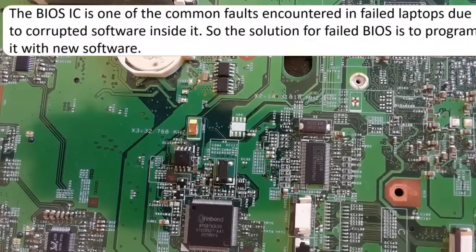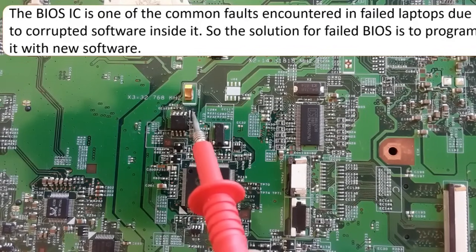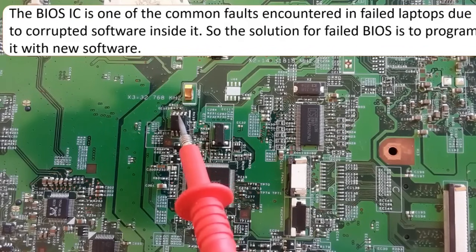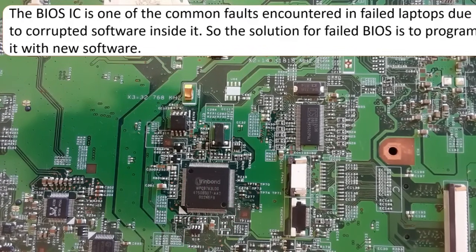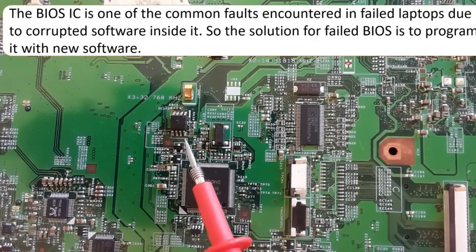See the BIOS, the basic input output system IC. Here, as you can see, we have this motherboard. We have the Super I/O. As you can see here, we have the BIOS. Okay, you can always find the BIOS near the Super I/O. This mark means pin number 1 for the BIOS. So here, as you can see, this is pin number 1. Okay, 2, 3, 4, 5, 6, 7, and 8. As I told you, the BIOS is usually near the Super Input Output IC. Okay, so we're going to see many motherboards in this course.